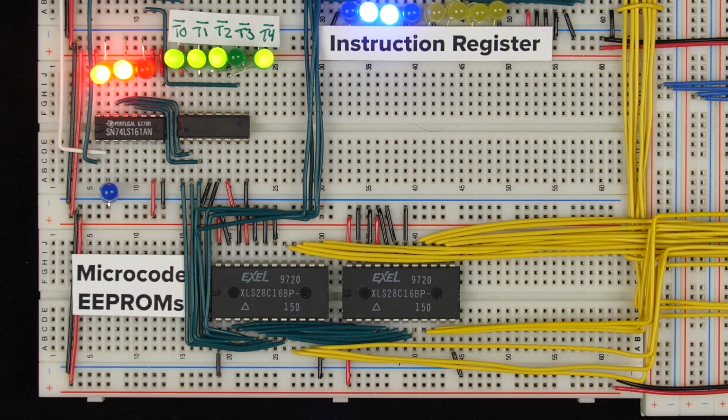And that way, the behavior of an instruction could be different depending on whether one of the flags is set. In most cases, it'll be the same, so we'll just have to program the same thing regardless of what the flags are set to. But for our new conditional jump instructions, we'll be able to do something different. So for jump carry, when the carry flag is set, we can have it actually change the program counter, but for jump carry when the carry flag is not set, we can have it do nothing. So let's hook that up.